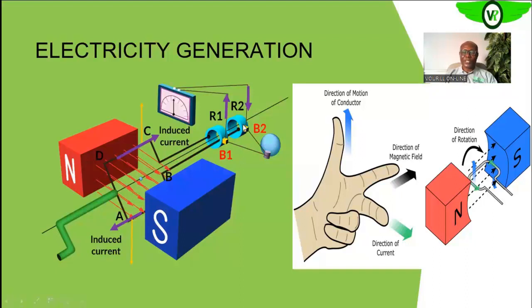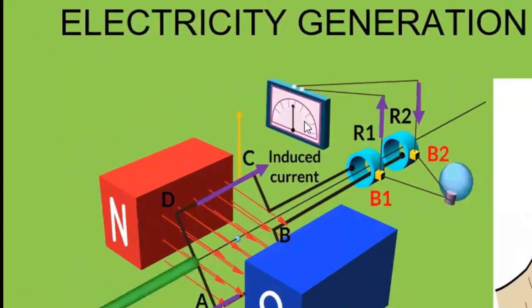The slip ring is the means by which we evacuate whatever is generated in the armature out to our load. So this could be our load, or this could be our load. Are we getting it? This kind of arrangement is known as the stationary field, because we have the field stationary on the stator.